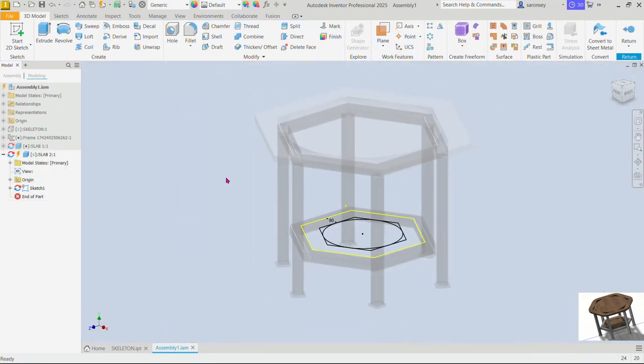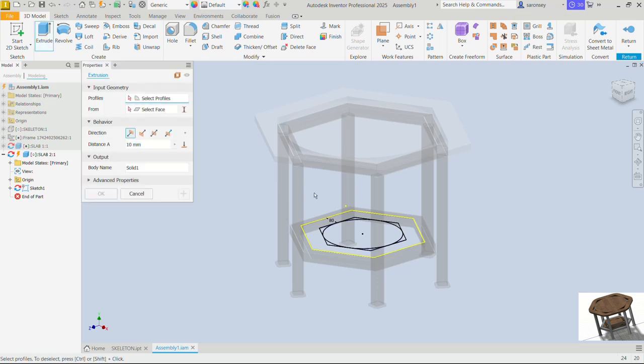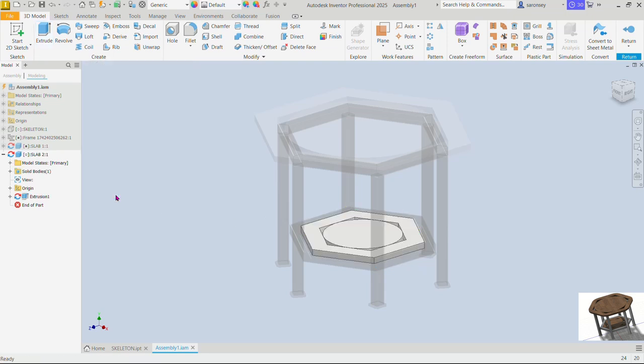Double click the scroll mouse button and we would extrude. The profiles are going to be this one and that one, but we want to reverse the direction of this extrusion, so we pick the second option here that says flipped. The depth or the distance of this extrusion is going to be 30, just like the first one. The preview is fine. We can OK.